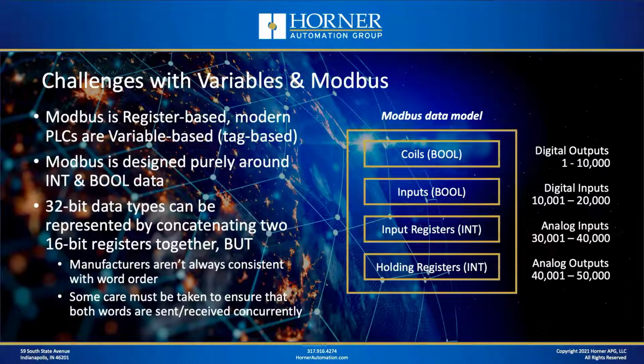Okay, what are the specific challenges with using variables or tags in your PLC programming environment or your OCS programming environment, and using an integer-based, register-based protocol like Modbus? Well, basically, Modbus is register-based and all the PLCs are variable-based. So that's the first challenge. They're different. Modbus is designed purely around integer and Boolean data. When it was invented, there was no 32-bit IEEE floating point data format. That didn't exist yet. Double integer data was way less common.